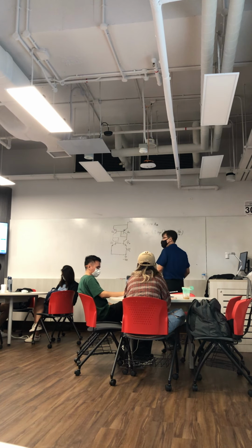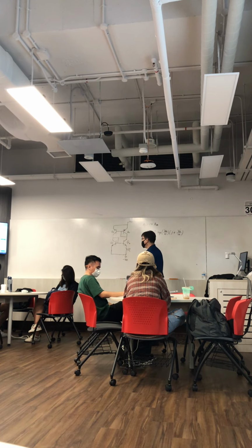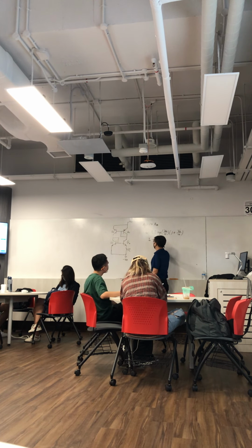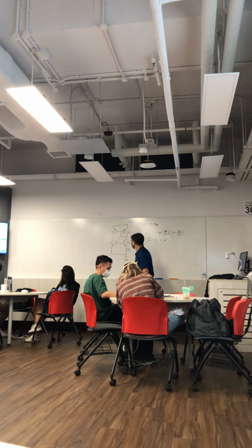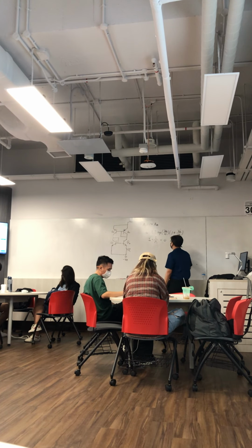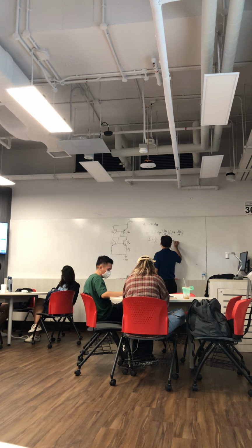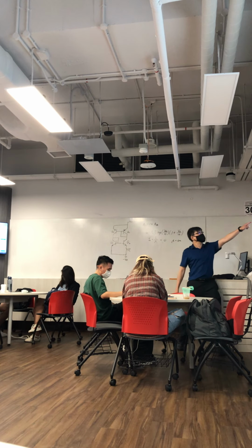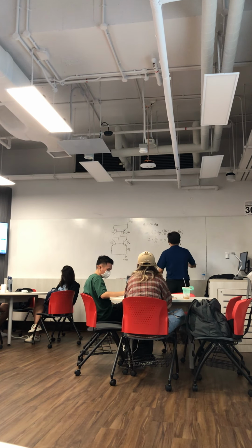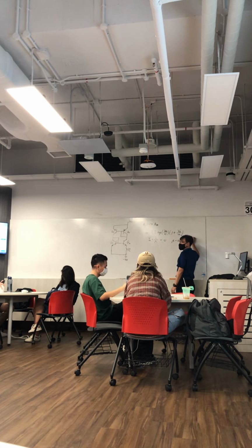Infinite current gain means beta equals infinity. When beta equals infinity, remember, base current equals collector current over beta, right? If beta is infinity, base current equals 0, right? So that means there's no base current. We assume base current equals 0. This is because beta equals infinity. That's the question here. Then secondly, ignore early effect means that VA is equal to infinity.